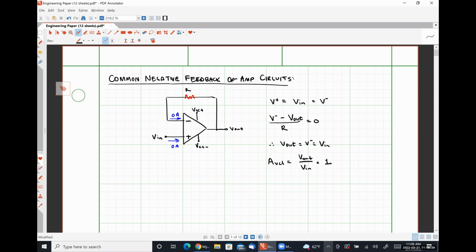Okay. So if you had something like a sensor that was running off of using a piezoelectric crystal to convert some sort of mechanical deformation into an electrical signal, that does a good job at creating voltages, but a pretty terrible job at creating the associated currents as well.